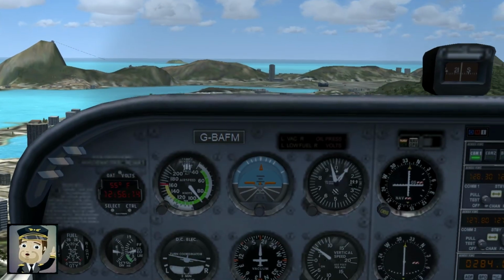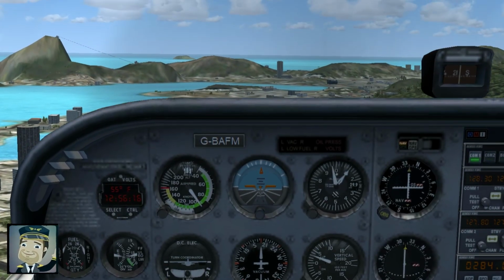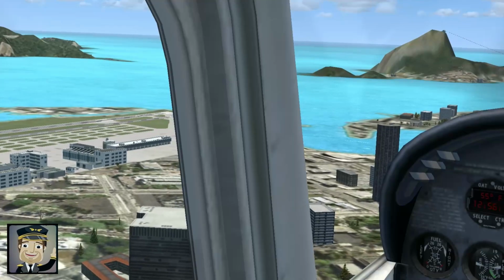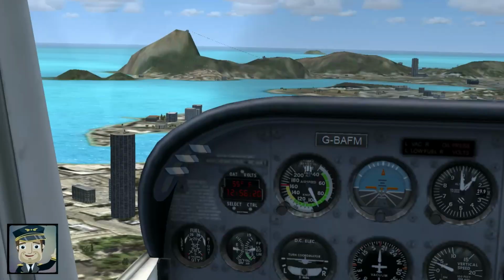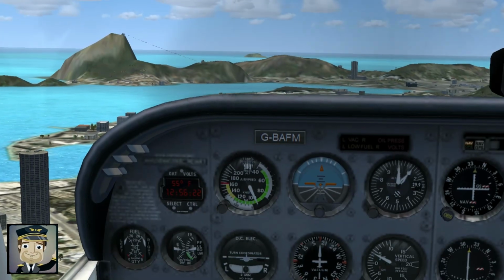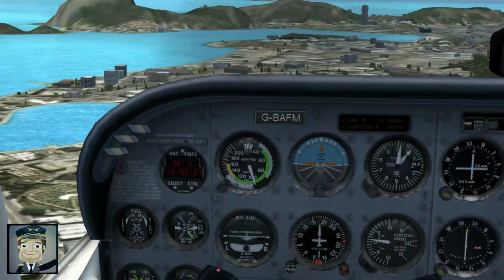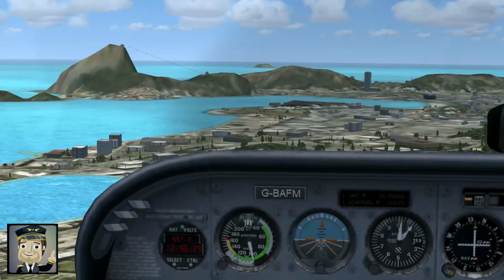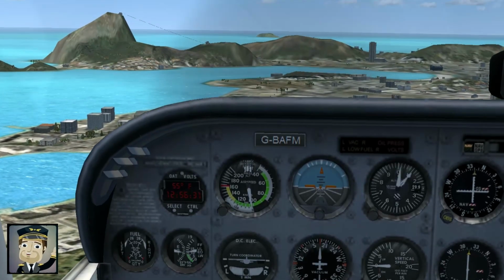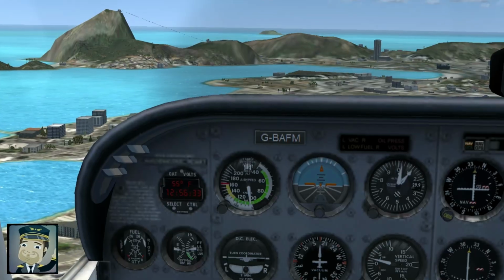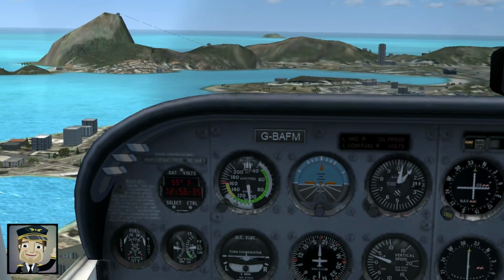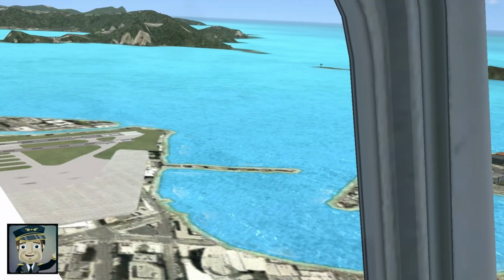The upwind leg is the initial segment flown directly above and parallel to the runway in the same direction used for takeoff. It is the extension of the takeoff roll after becoming airborne, or the segment used following a go-around to regain altitude before re-entering the pattern. With a strong headwind pushing against the aircraft's nose, the airplane gains stable lift but demands more engine power to maintain a proper climb rate.